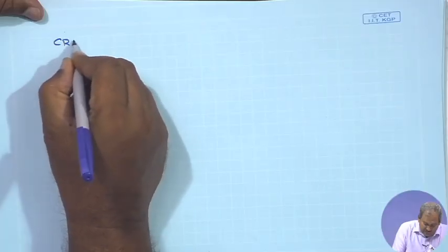The same happens for the case of a sphere. When you increase the size of the sphere, the area available for conductive flow of heat out of the sphere will increase. So, the concept of critical thickness of insulation can only be found in those geometries where the area increases with increase in distance from the center point or center line. So, I will quickly show you what the critical thickness of insulation is.